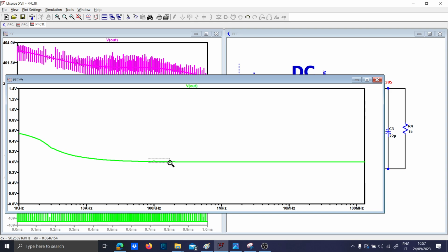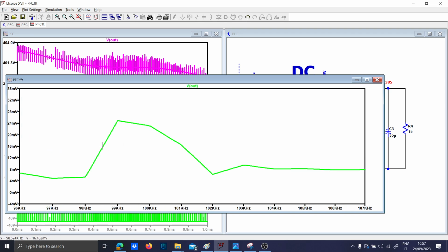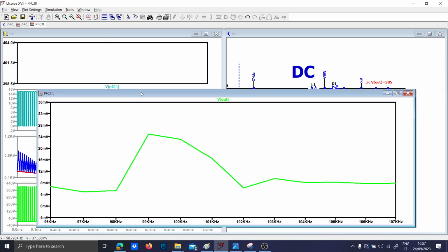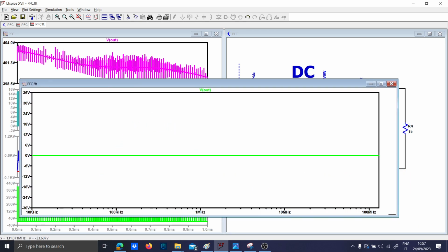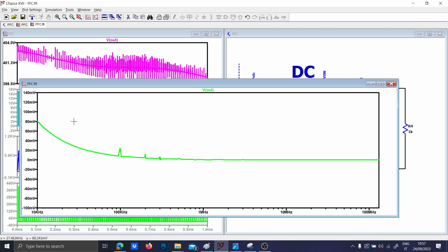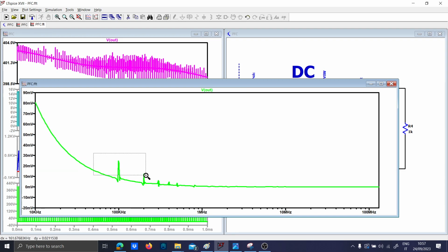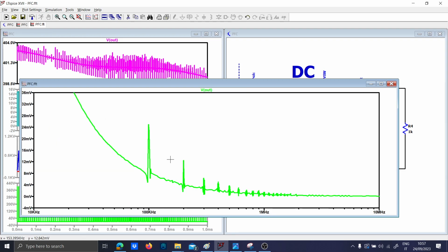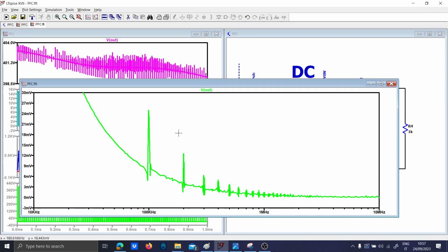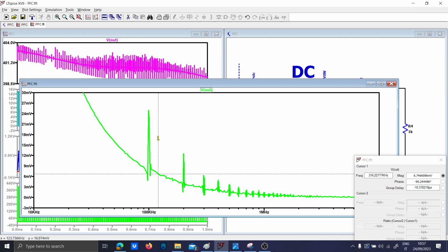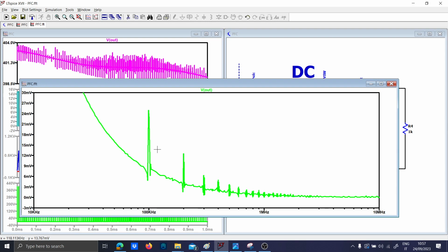The thing is that here at 100 kHz, you have the switching frequency component, and as you can see, it is not that high. It should be higher though, but I don't see anything on the spectrum. But it is this 100 kHz. Oh, now you can see also the replicas. The replica of 200 kHz should be here. Yes. So this is the first harmonic, second harmonic, third harmonic, and so on, given by the ripple of the converter.